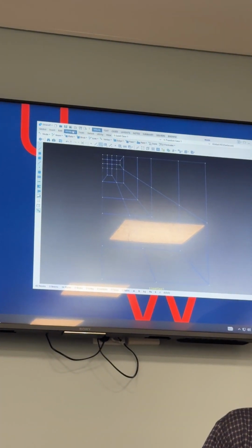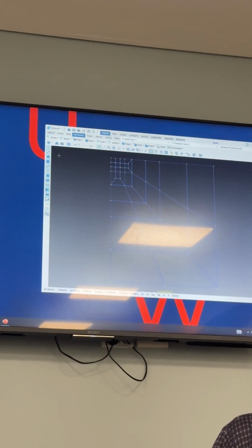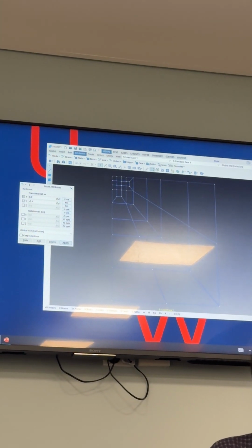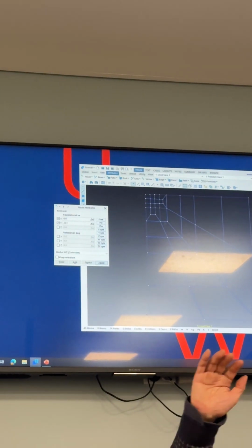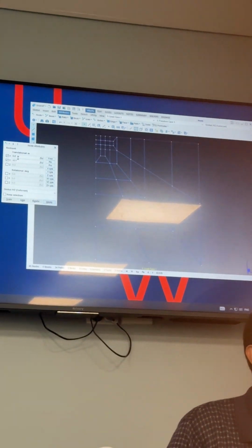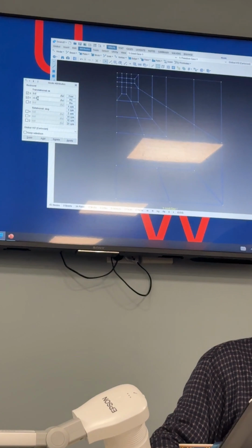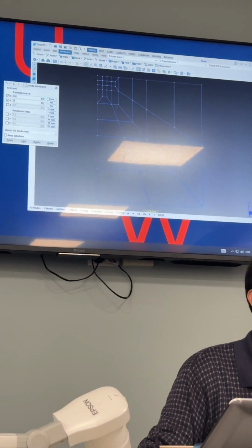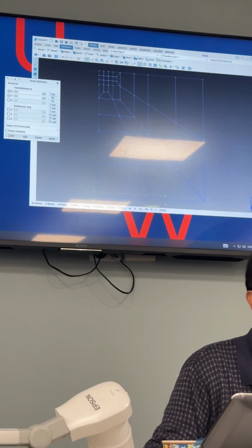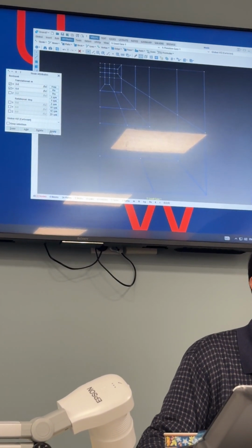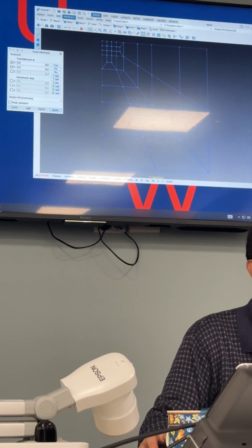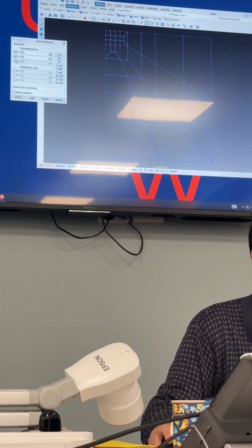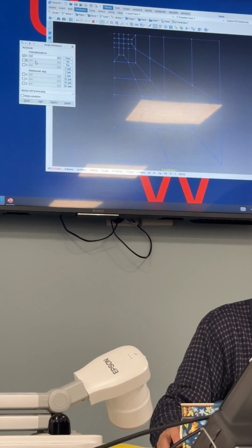Visual, attribute, nodal, constraint. We're going to enter the base boundary condition first. That is, no displacement in x direction, no displacement in y direction. So x is 0, y is 0. After you select it, you select all the base nodal points, apply. Then you choose the set boundary condition. X is 0, y is free.